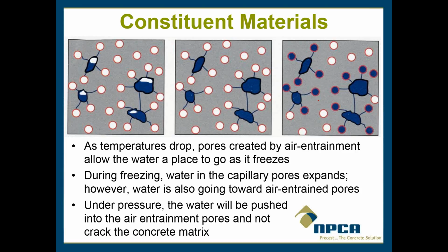Yeah, it just says, air entraining can also be added for workability. Some people don't even use it for freeze-thaw. This particular person's using it, but it's not for freeze-thaw. It's actually for workability. So it kind of acts like ball bearings, so it'll aid your workability, and it'll actually enable you to use less water. So that's another good reason to use it.